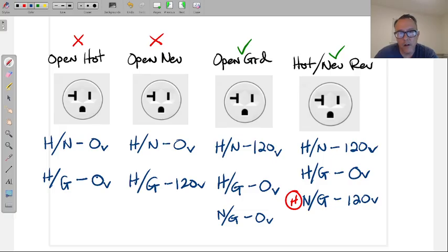If you don't have a load working on the outlet, like over here, sometimes I like to remove the outlet when things aren't working because, one, I get to do a nice little visual check, see what's going on under the hood, right? See what's going on in there. I have literally seen no neutral at all in the junction box, especially when there's conduit and you have to pull wires, and believe me, we forget a wire or two. So opening up the device is good.